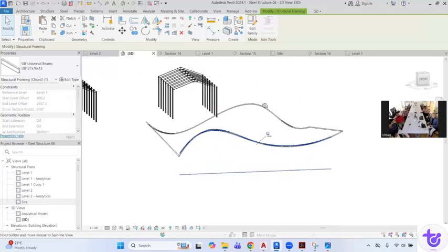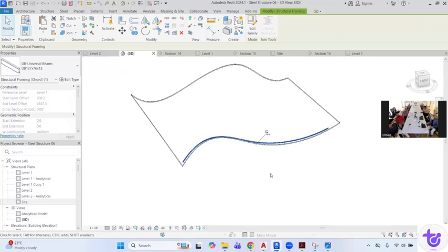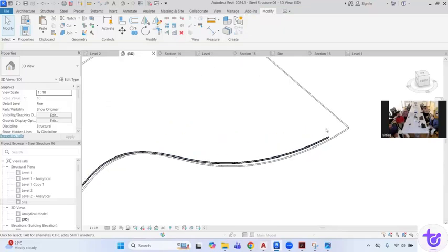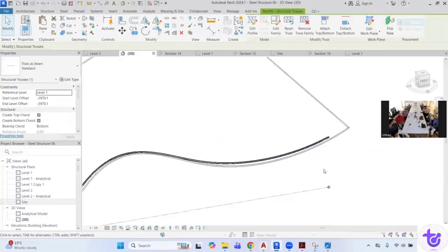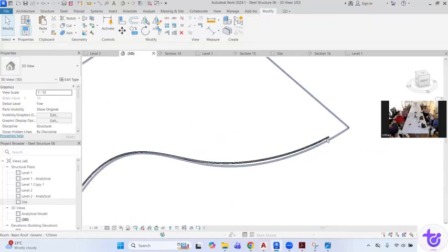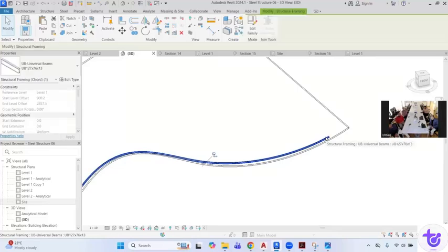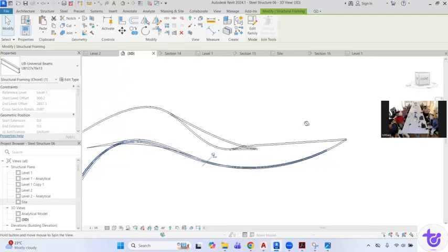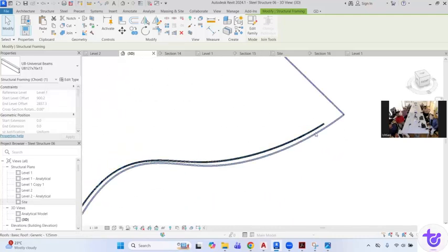So this is how you are going to deal with this. You cannot explode a truss the way we explode in AutoCAD, but it will remain a truss. So now it is a matter of selection whether you want to select it by the tab key. It will give you a framing, and you can put the framing tag also. So that's what you can do.